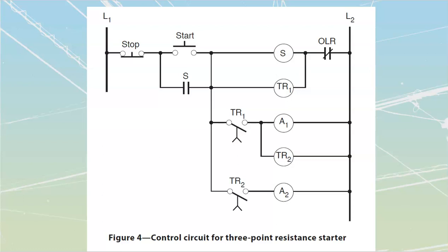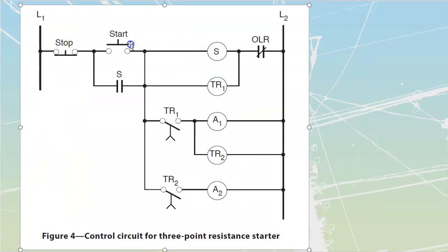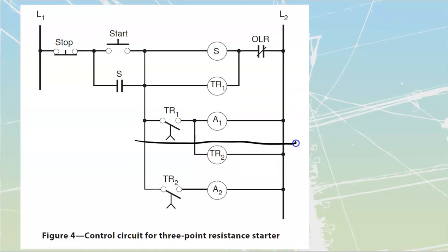And this control circuit is simply the exact same thing as our previous one, other than that we have now added in a second timer. So everything that we did before above that line stays the same. All we've done now is when we've started up our first accelerating coil, we start a second timer, which is then going to time out my timer number 2. We'll follow it through. In this one here, once again, we'll just bring power up to where it would normally be stopped inside of my control circuit here.